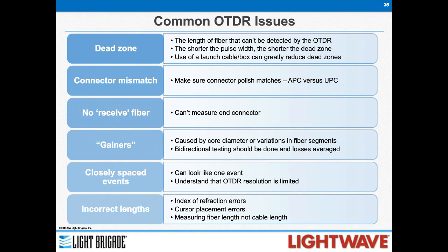What it does is it gives the OTDR some time to settle down after the launch, and allows you to take a look at the very beginning of that link, the very first connection, the very first patch panel, if that's what you're going through. It allows the OTDR to see that and report that accurately. Without a launch cable of some kind, you're going to lose everything that happens in the first few 10, maybe up to 30, 40, 50 meters. You won't see that in your OTDR. It gets lost in the noise. So you want to test with a launch cable.